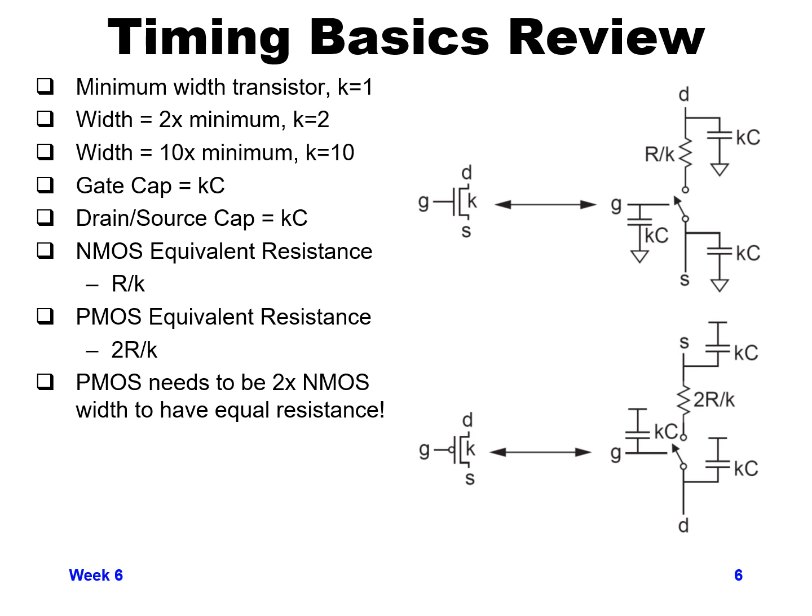C is the unit capacitance, the base unit for a minimum width gate transistor. So the gate capacitance value is going to be K times C. The wider you are, the more capacitance you have. Similarly, the drain and source cap value is going to equal K times C.